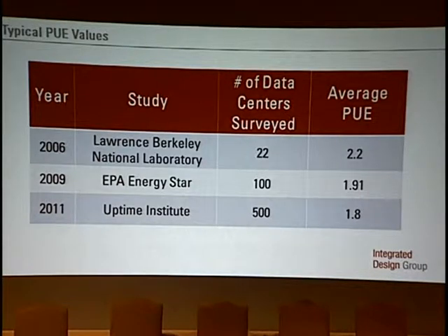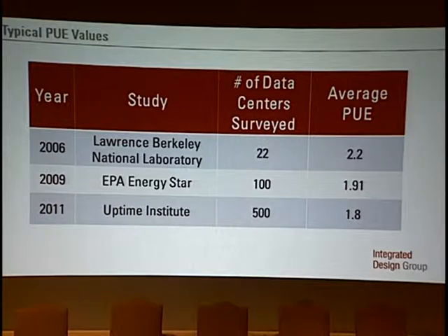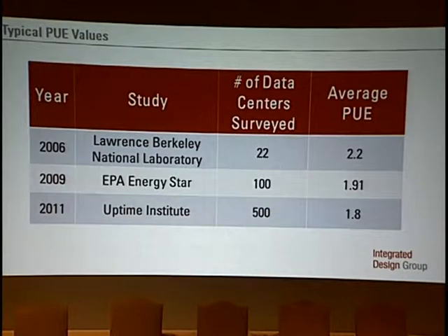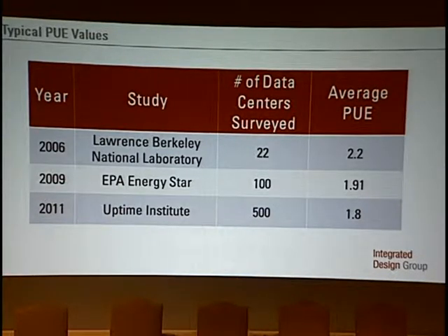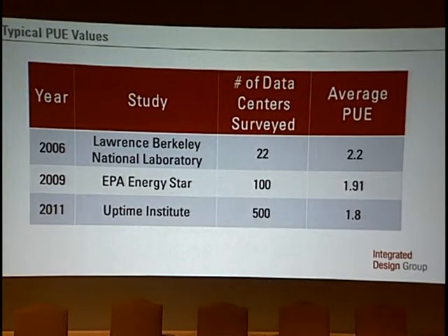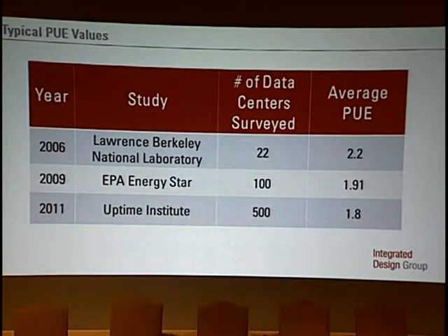So here are some documented PUE studies representing averages of many types of data centers in many locations. Unfortunately, some of the reporting requirements of some of these studies really weren't very well defined. It's hard to tell where the measurements were taken in the building and whether these are annualized or instantaneous or whatever time period was used to calculate these PUEs.